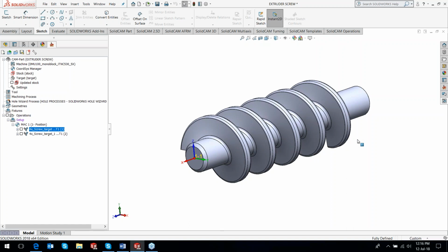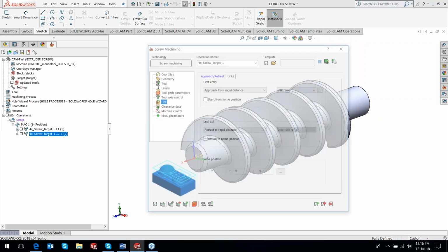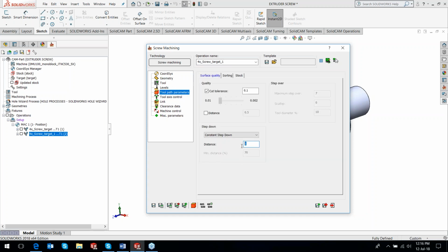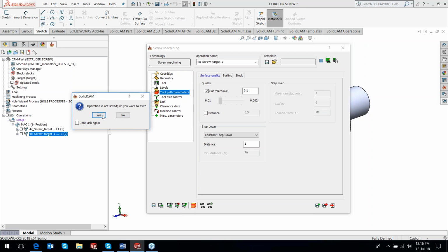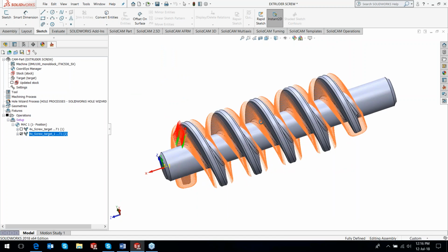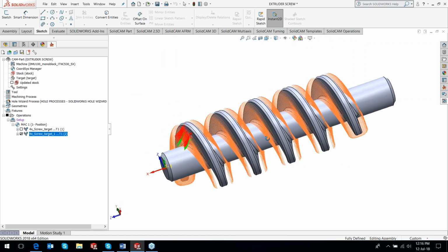The same technique then is carried over, and instead of doing roughing, we basically will do the finishing operation. And you can see that I've now given the actual limits out here. I don't want it to go anywhere else within a specified distance. I would like it to machine. And it simply will ask, what is the depth of cut? 1 millimeter in this case. Everything else remains the same. What do I get here? I get a pretty nice toolpath here, which runs all around the part.